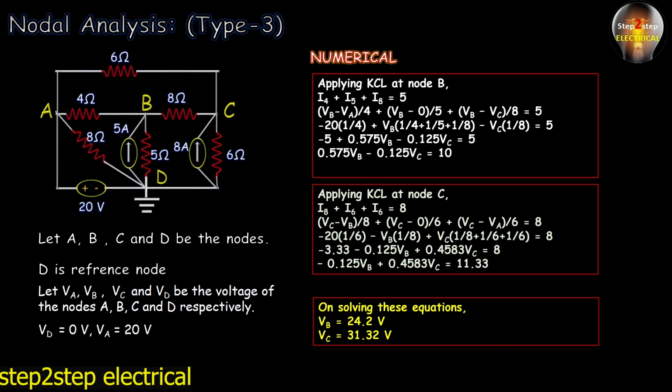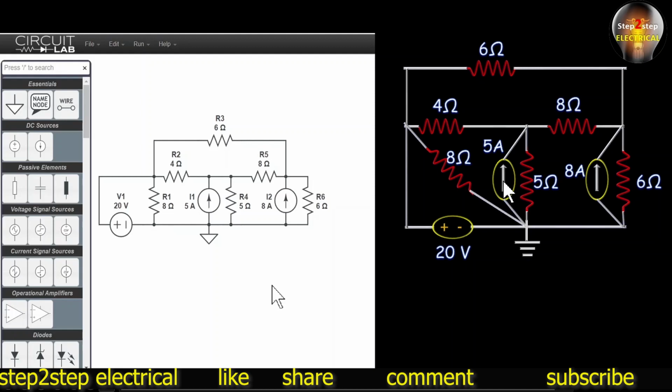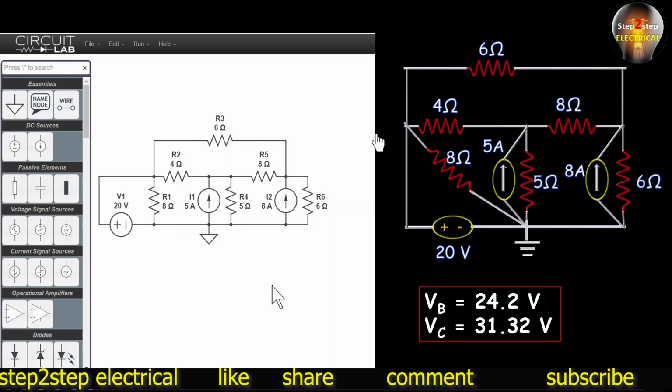So it is easy. Now let's verify our result with the help of Circuit Lab. So this is the circuit that we have solved, and now I have also drawn this circuit in Circuit Lab. Okay, and for proper examination and verification, let's write the result we have obtained. So this is the result, that is VB equals 24.2 volt, VC equals 31.32 volt. Sorry, this is 20 volt. Why? Because this is directly connected with this node A. That's why it is correct. Okay, this node voltage is 24.2 and here in the result 24.2. So both are correct. Again here we can see that it is 31.33 and here it is 31.32 volt.